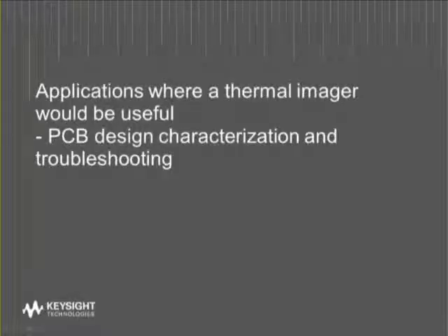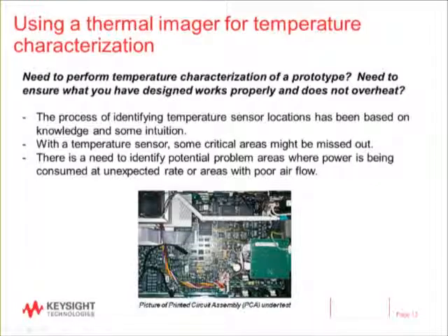So next, let's look at another application that is gaining popularity in R&D: PCB design characterization and troubleshooting. If you're an R&D electronics engineer having completed your first prototype, it seems like everything works as designed. However, a temperature characterization of your design is necessary to ensure that its components do not get overheated through normal use. Usually with your nodes, you can theoretically derive where the most power is dissipated and identify the potential problem areas, but a flaw in the design where power is being consumed at an unexpected rate might go undetected.